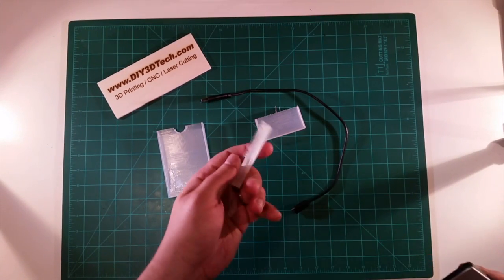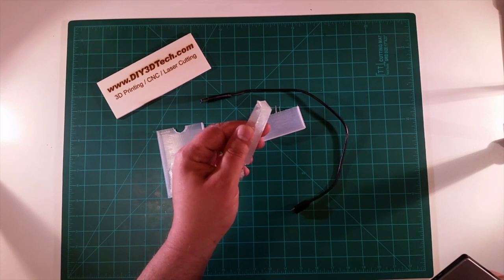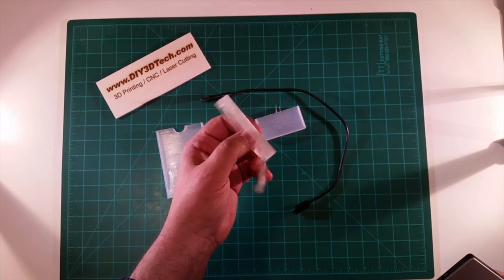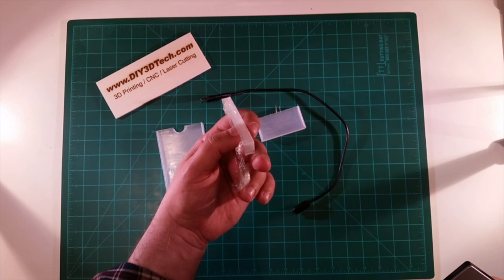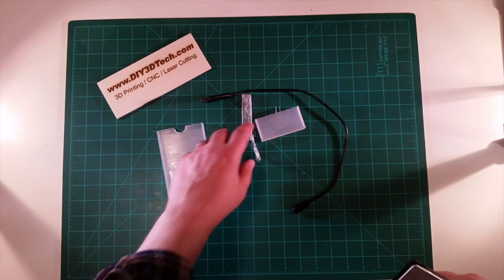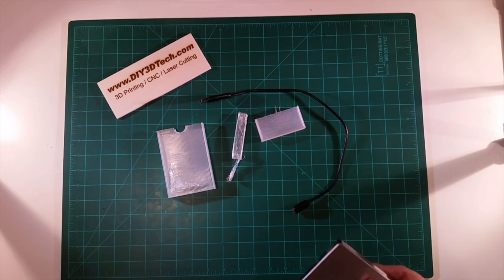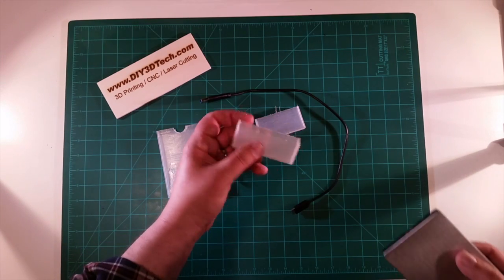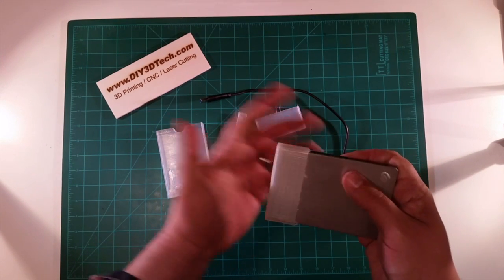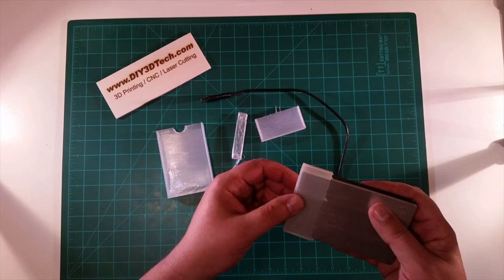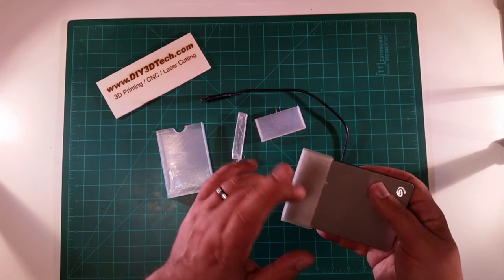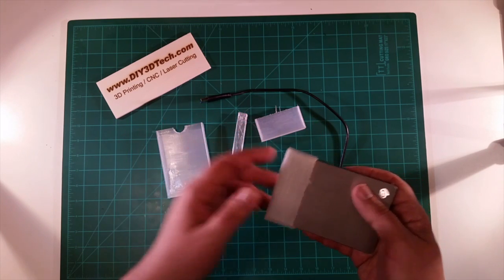So I did try reprinting with infill rather than the equivalent of vase mode in Cura, and this is what I got. So not good. I did jump back up from this one to this one, which is 1.5. It fits beautifully, comes out nice, but the problem is now I'm having problems with the extruder pushing the TPU.